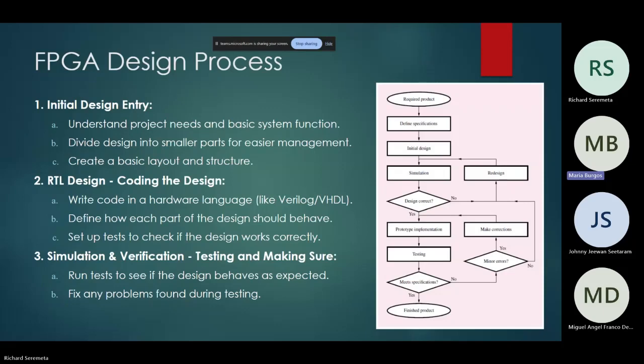The next stage is simulation and verification, testing and making sure that the project will work as it should. Here, test benches are used to simulate the design and verify its functionality. Test benches are like virtual environments where one can simulate how the design behaves under different conditions.